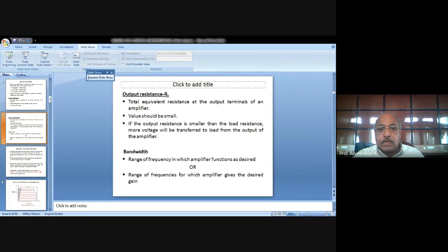So between these we give the VCC, and this VCC will reverse bias the collector base junction. Here this is positive and this is negative, P and N. This N is connected to positive, and this is P. So this is reverse bias. What about this one?